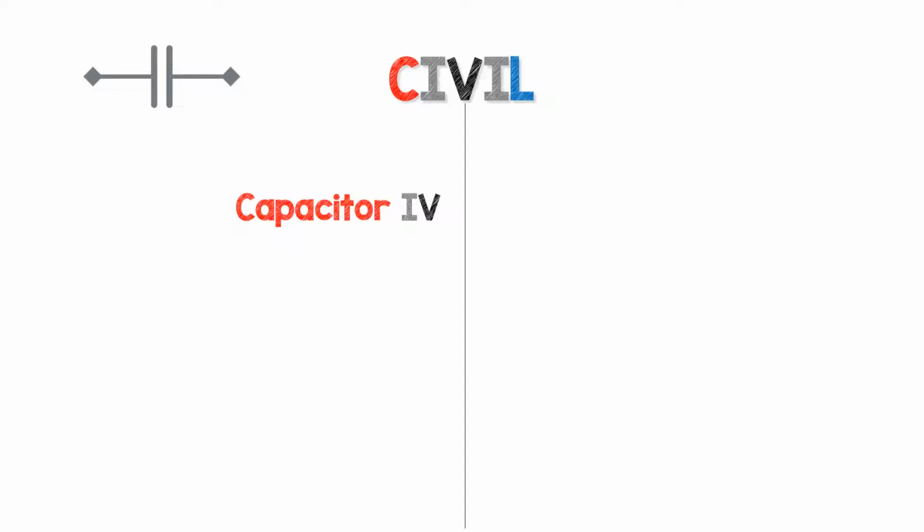On the right hand side of the word we have VIL. And this means that in an inductor, L, the voltage V is in front of the current I. So current lags voltage in an inductor by exactly 90 degrees or 1/4 of a period. Phase difference is defined as how much the current leads in front of or lags behind the applied voltage.